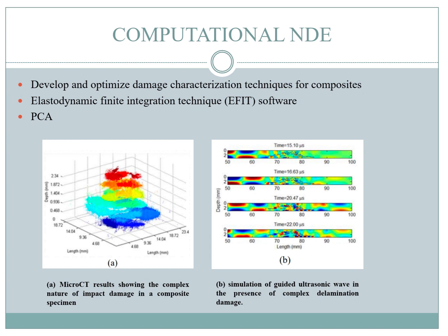The simulation results have led to an approach for the detection of hidden multilayer delaminations. These simulation tools can also be used to develop a new rapid quantitative method to analyze NDE data such as PCA. PCA has been extensively used for the reduction of flash infrared thermography data, but it is also computationally intensive, and potential issues with large defects are being addressed.